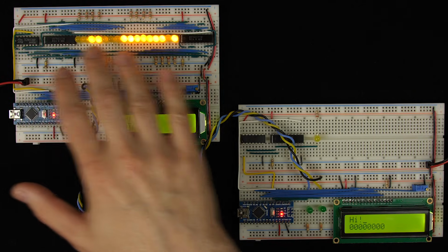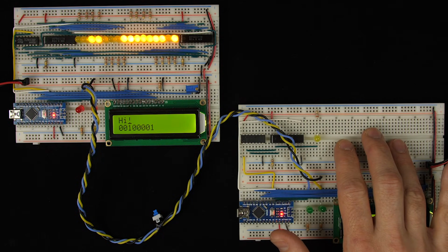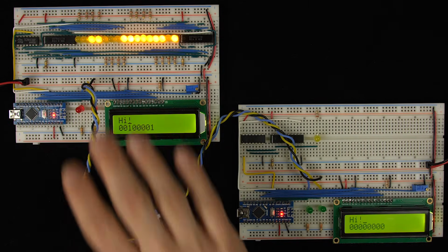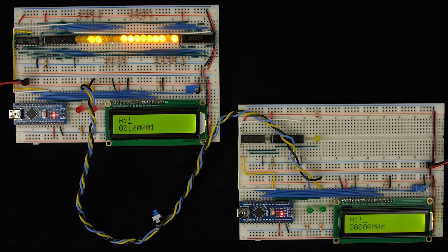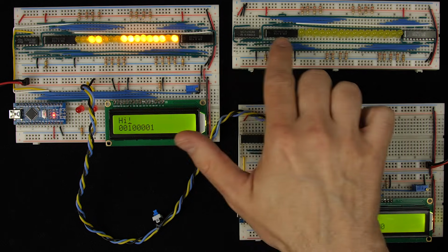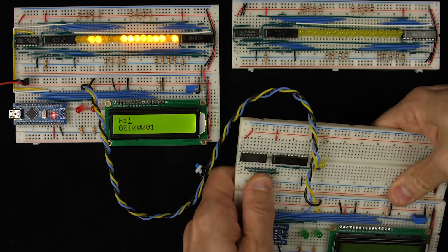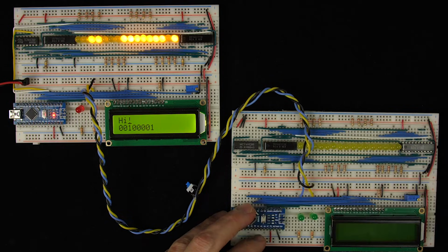Okay, so now that we can compute the CRC, and we're doing that on the transmitter, we need to be able to compute the CRC on the receiver as well. So we need another circuit identical to what we have on the transmitter over on the receiver. So we need to build that now. Conveniently, I've already prepared one, and so this is identical to this. It should be exactly the same. And so I'll just go ahead and swap that in here in place of the parity circuit.